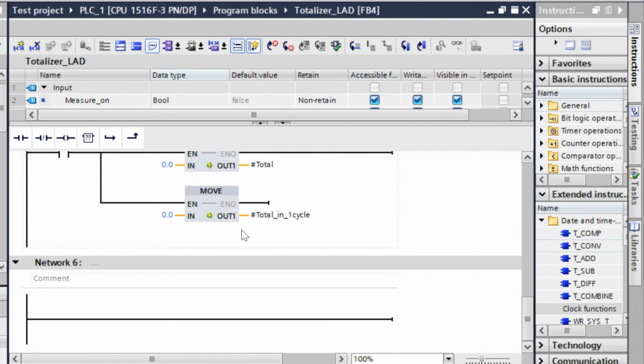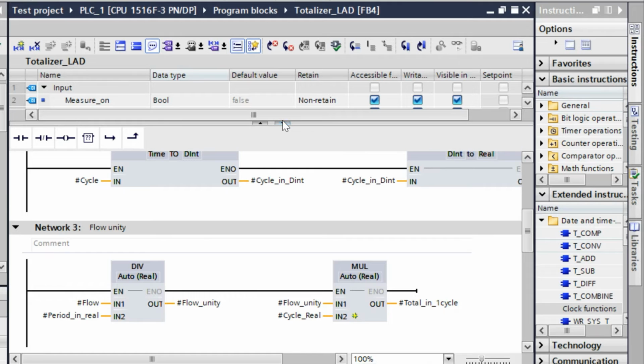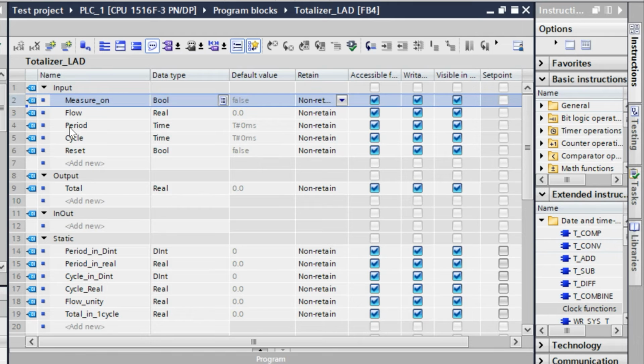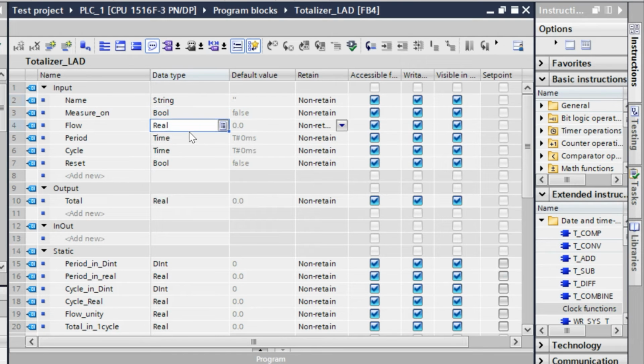this is our application function. This is our function for totalizer. You can give another input, okay, that is not used for calculation. Here we'll use another tag. It is just to define the totalizer name, because sometimes you may have more than one totalizer. So which totalizer is for which one, you can define by the totalizer name. So the data type is string.